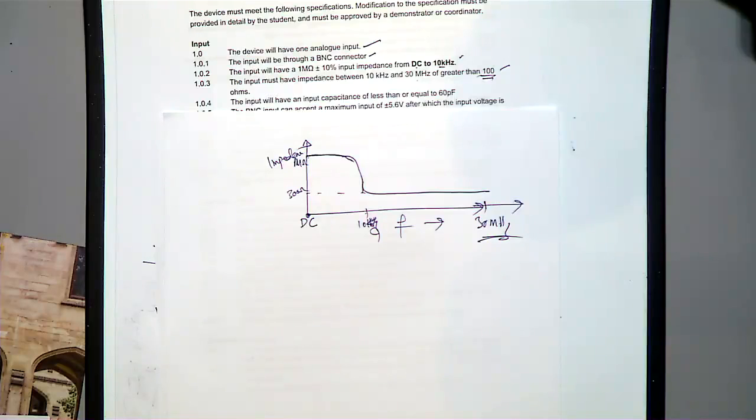If you want to get something like that at the input, then you know that using a resistor alone you can't get it. So you have to think of how you can get an impedance that depends on the frequency. If your system has that type of specification, what element can you add? Yes, you can add some capacitors and make an impedance network, then you can do it. We will do that later.